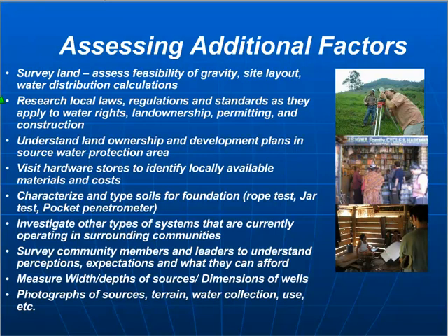Understanding the local laws and regulations is extremely important. In certain countries, there's standards of what the per person demand needs to be. There's standard tank designs that all the local contractors use, and so you need to be aware of those so you can make sure that what you're doing is appropriate in the context of water projects in that country.